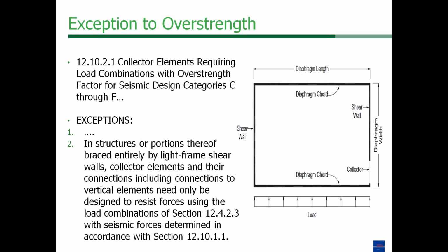So what's important to recognize here is that section 12.4.2.3 is the section with just basic load combinations, so there's no overstrength required.